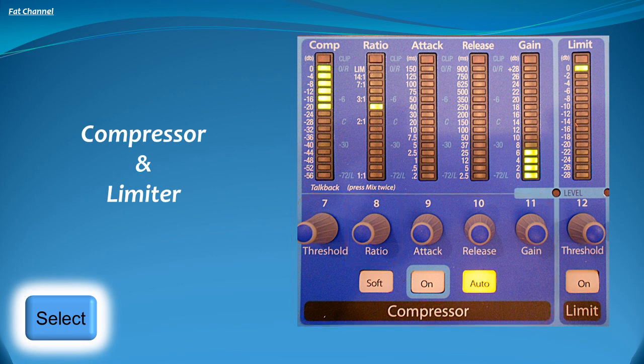The SL24.4.2 also has a limiter function. Unlike a compressor, a limiter is a brick wall. It provides a dead stop to volume increase. The signal output will be limited to some absolute value. Limiters must be used carefully as they can distort sound. Both the compressor and limiter sections of the SL24.4.2 can be turned on or off via their on buttons without having to change any of the individual settings.